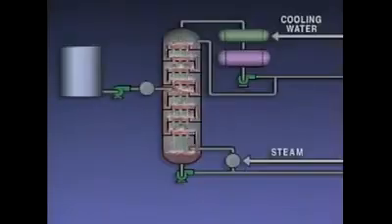If a distillation tower worked perfectly, it would produce pure products. Unfortunately, that's not the case. The lighter products usually contain some heavier fractions, and the heavier products usually contain some lighter fractions. This is sometimes referred to as overlap. Distillation systems use several methods to help maximize the purity of the products.